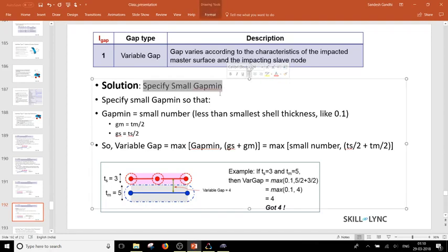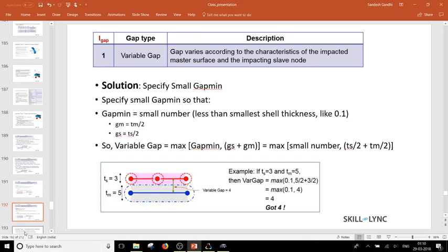That gap minimum in my application, I typically define as 0.5 mm or 0.6 mm, and that is really up to the particular engineer. But once we start following some practice, we always try to stick to that, and then we can change the rest of the system accordingly.